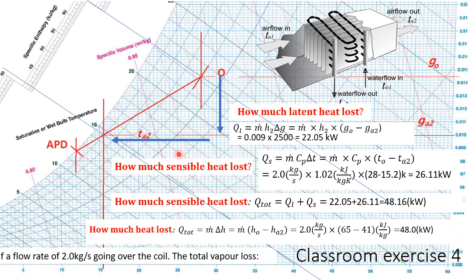So you can see, using the psychrometric chart, enthalpy really means the energy change of the air. Okay, so using this example, we can understand better the two components, sensible heat and latent heat. And also these two components make up the enthalpy. And also from here, we know the energy lost from the air will be gained by the borehole water. Okay?